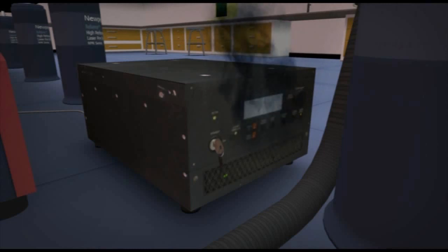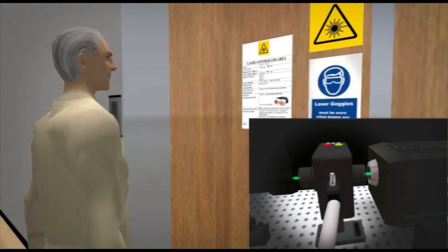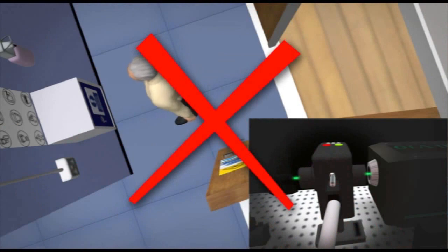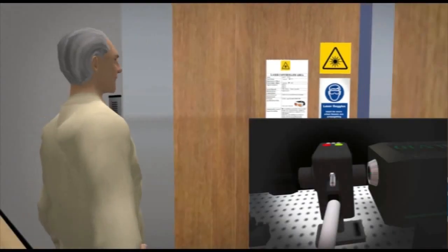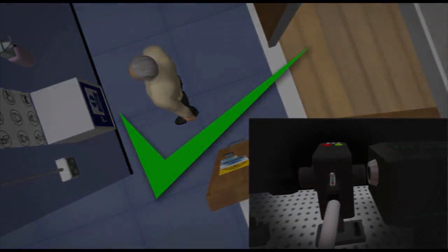Single fault conditions are important because the classification of a laser is partially dependent upon the output power. If this increases because of a broken component in the power supply and allows more current to be delivered, this could push the laser into a more dangerous class. Likewise, the failure of an interlock shutter, which is supposed to trigger if the door interlock or enclosure interlock is tripped, can cause a hazardous situation to occur.